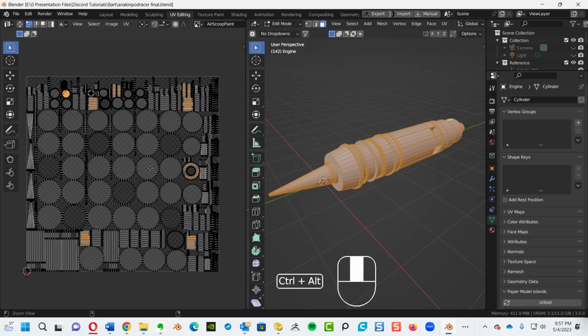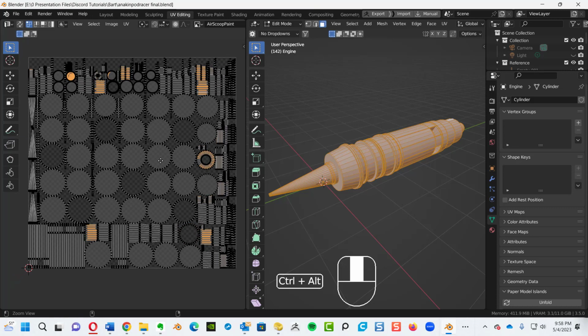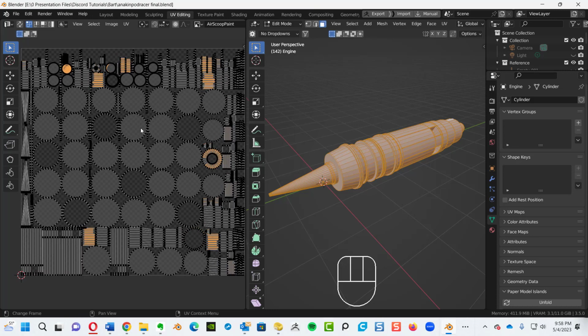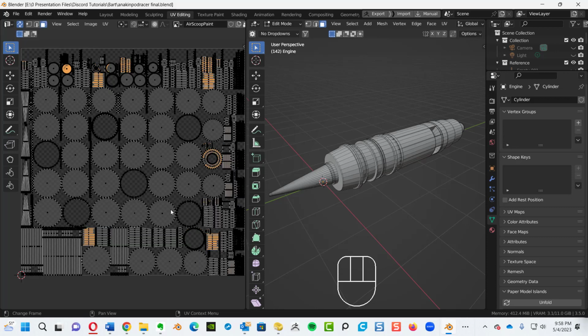I tell you what, I'm looking at this thinking that this could be done a lot easier, and I'm going to share that with you now in terms of UV mapping. So if we select each one, I'm going to come over here and just hit the L key. I'm going to turn everything off. Now all of your UV maps went away because I didn't give it the option to make sure that they're always visible. On the top left hand corner, you see your two vertical arrows right up here. If we click them, they'll always show.